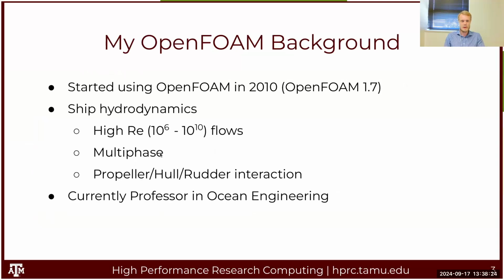Just very quickly about my OpenFOAM background. I started using it in 2010. Back then it was version 1.7. I've been using it almost exclusively for ship hydrodynamics. That's high Reynolds number flows, 1 million to 10 billion. It's multi-phase. There are rotating propellers and interaction between rotating propellers and rudders and moving hulls.